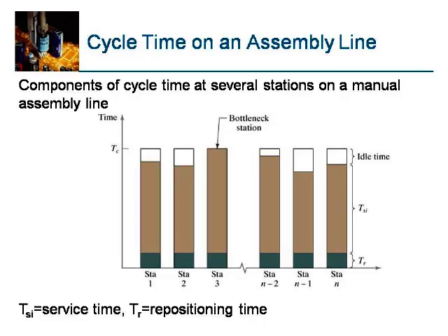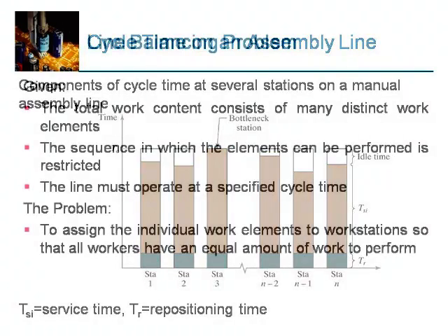This idle time is slack time, and it can be used for repositioning purposes. And in this workstation, there is no idle time, and this is going to be the bottleneck station, where the time is very tight. Prior to that there is a lot of slack time, and the work parts get blocked here, and the workstations after this will be starved.